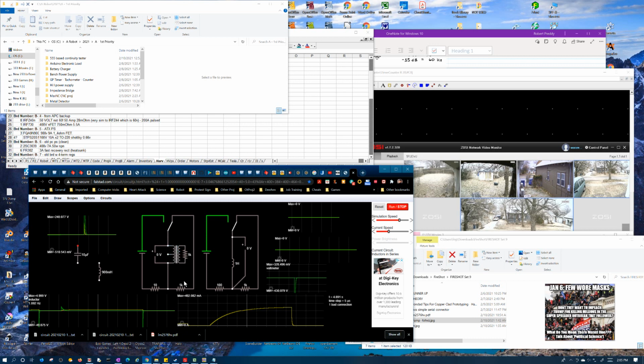I'm not sure about it. That makes me wonder, because again, I would expect to see kind of the same voltage on both sides, given the fact the impedance is the same on both sides. But it's not, but it does make sense that this would be 10 turns here, 10 turns here, and then 10 turns here. If that's the case, and this has twice the inductance, so yeah, you're going to get half the voltage here.